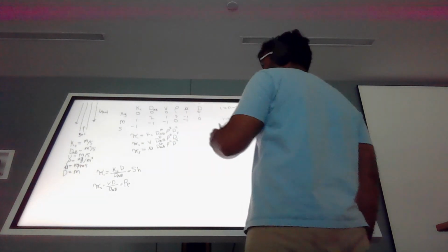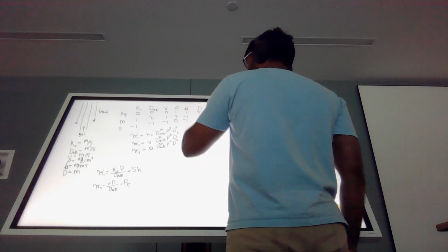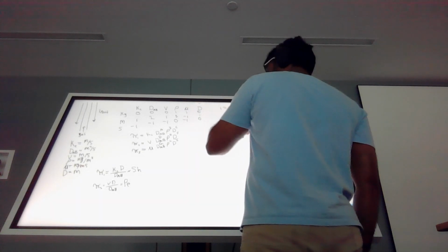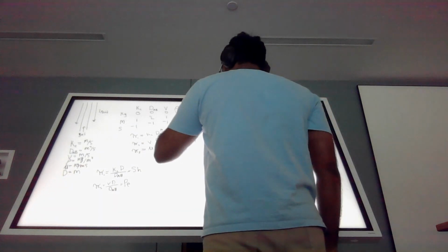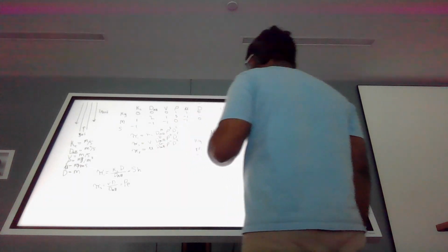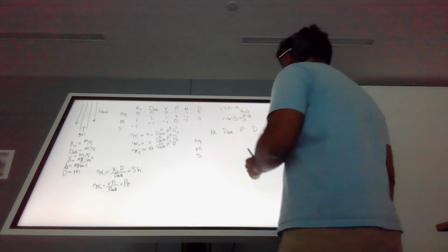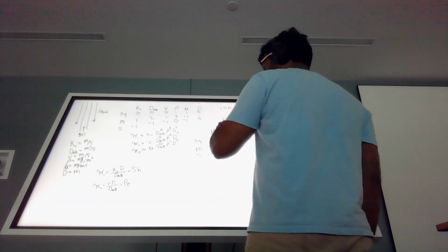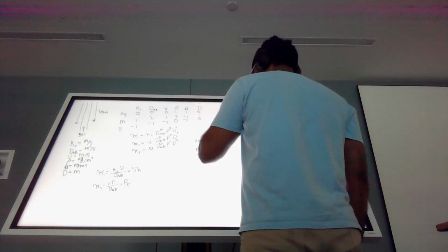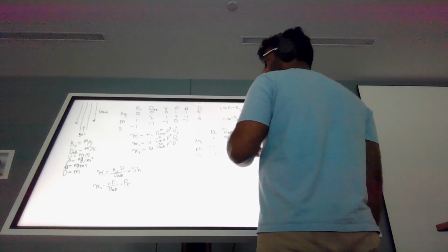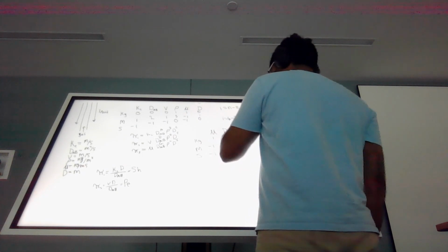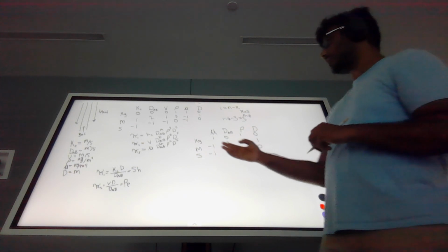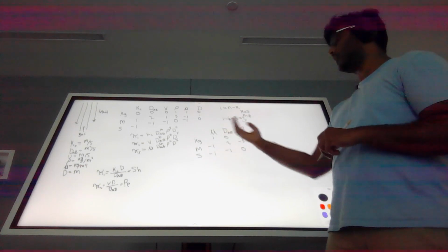So we're going to use the same exact matrix format as we did before, and we're going to write mu, DAB, density and diameter, and then kilograms, meters, and seconds. And we're going to fill out the matrix the same exact way that we did before. So we're going to say that there is 1, -1, -1, DAB. So it's 0, 2, -1. Density is going to be 1, -3, 0, and then 0, 1, and 0. And again, all we did was look at the power that each of these kilograms, meters, and seconds were raised to within the variable specific unit.